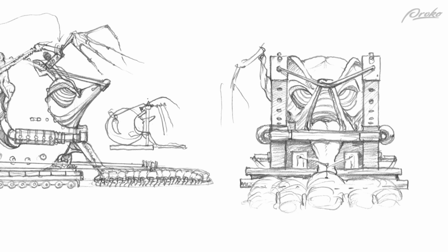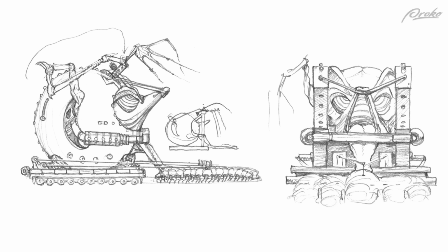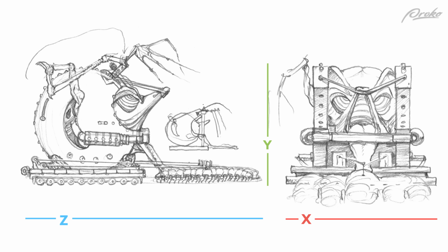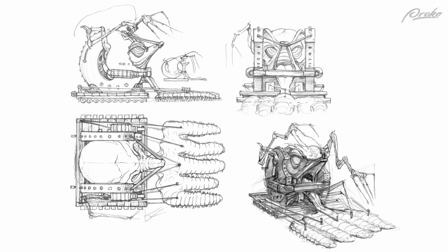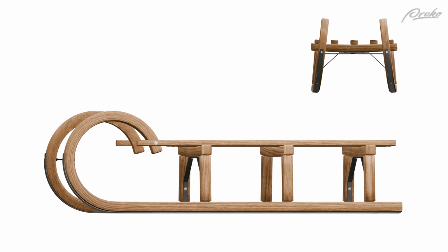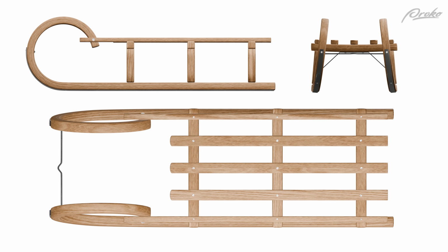The same thing goes on between the front and side, but with another mystery axis. The front view shows width and height. Who knows how deep? The side view knows. The side view, like the top view, knows how deep, but does not know how wide, which the other two views do.